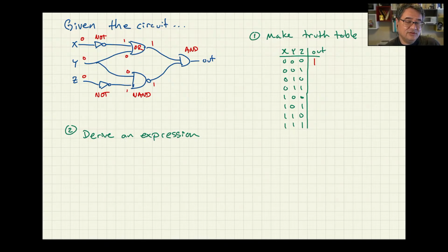Most TVs these days still have a composite input on them. The problem is that you've got the composite input going into a digital television, and the output from these computers was strictly analog. In fact, if you plug them into some of the modern televisions, they can't really display them at all because they're not displaying a true television signal. They're displaying kind of a fake one. Most televisions stick to the standard so well that they can't actually see the video that these computers output. So you have to connect them to an old-style analog television in order to see the picture on them.